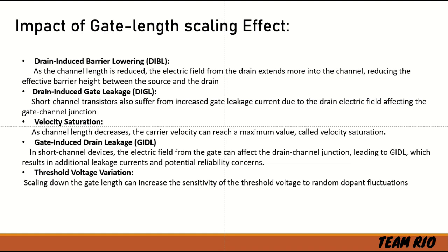Gate length scaling refers to the process of reducing the physical size of the transistor gate in integrated circuits as technology advances. The scaling has been a fundamental driving force in the semiconductor industry, allowing for higher transistor density, increased performance and lower power consumption in electronic devices. However, as gate length scales down, it leads to several challenges, particularly in short channel devices.